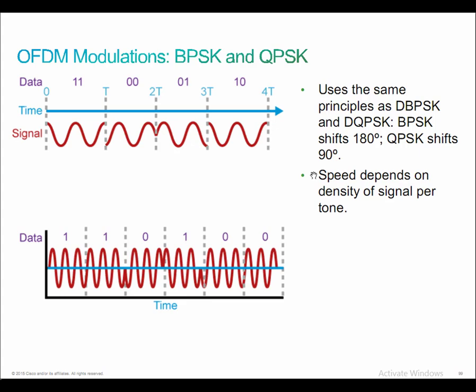Now you can increase the density of the information per subcarrier. It can go up to 9 megabits per second if you do, say, 187 kilobits per second per subcarrier. We can do this because OFDM prefers to send redundant information. So just like we saw with DSSS, we want to make sure that the message is received even if some bits are lost.